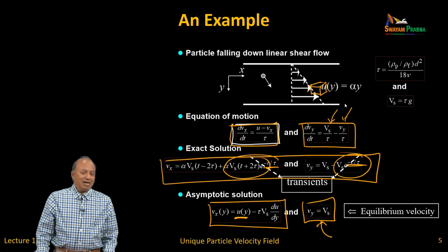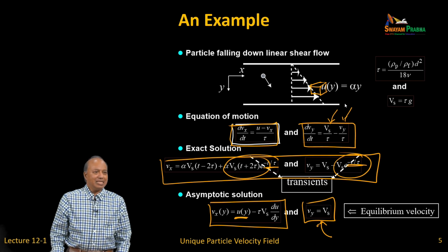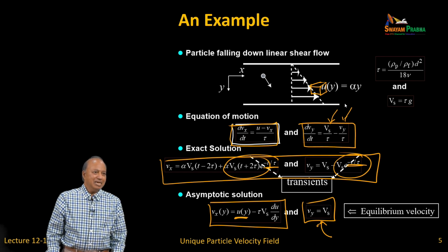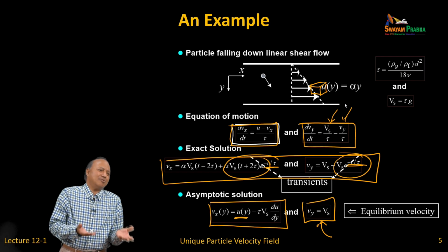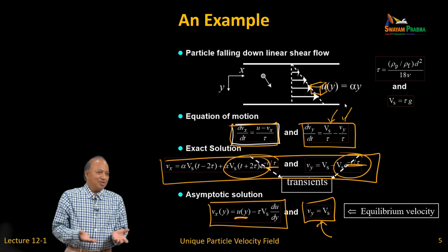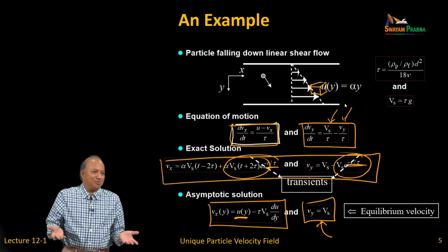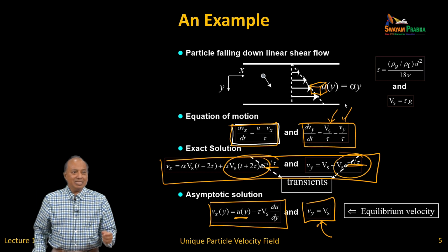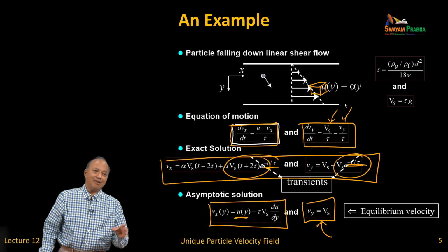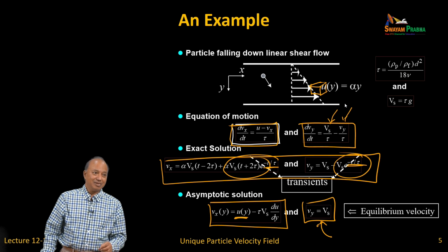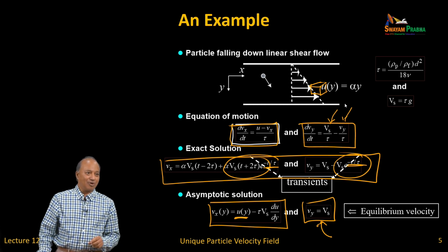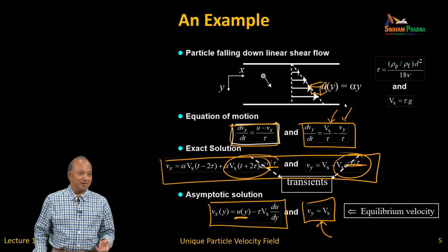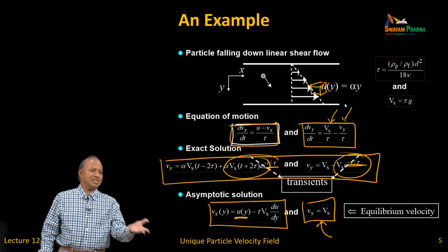So in this slide I want to tell you that sometimes you don't even need the Euler method, because particles follow the fluid pretty much. In the worst case, you can simply say V is equal to U. That means particles are just following the fluid. If that is the case, if you know what the velocity is, you only have to solve mass balance. You don't need to solve momentum balance in your Euler, because velocity is free. Same way the temperature of the particulate field, if it's so small, is the same as the surrounding fluid.